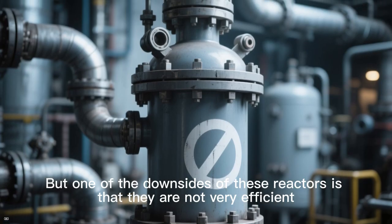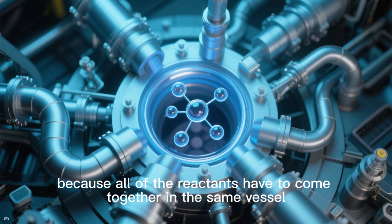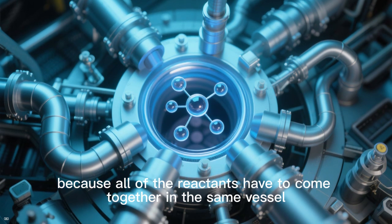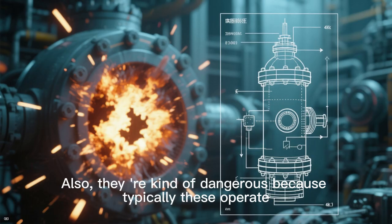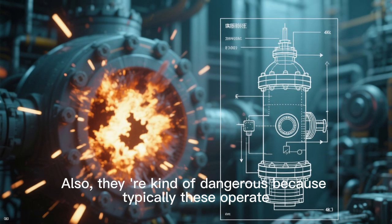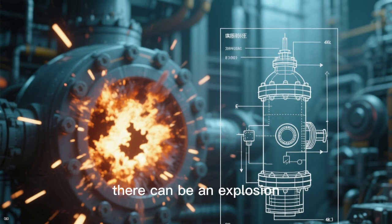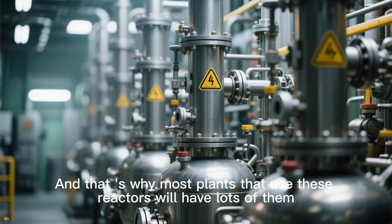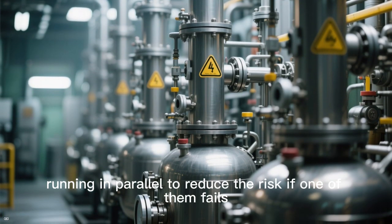But one of the downsides of these reactors is that they are not very efficient because all of the reactants have to come together in the same vessel. And that can lead to hot spots and runaway reactions. Also, they're kinda dangerous because typically these operate at high pressures, and that means that if something goes wrong, there can be an explosion. And that is why most plants that use these reactors will have lots of them running in parallel to reduce the risk if one of them fails.